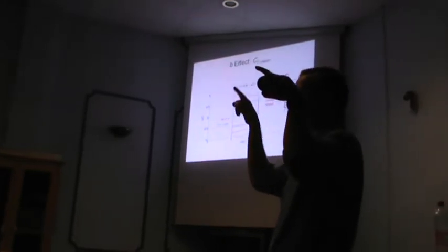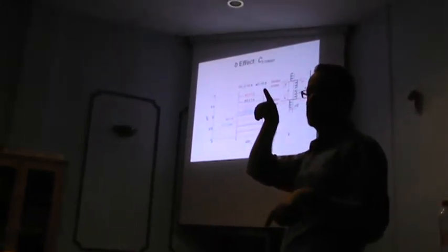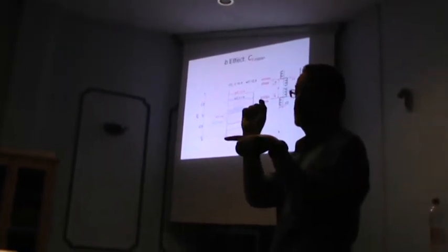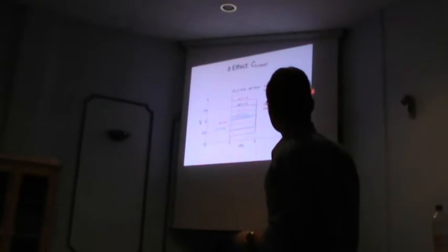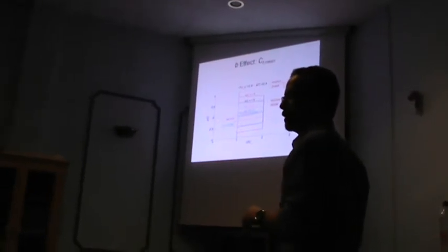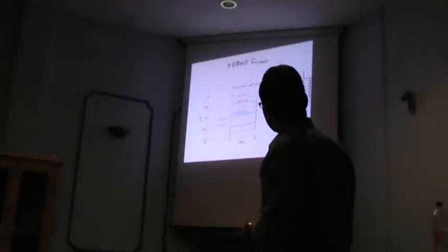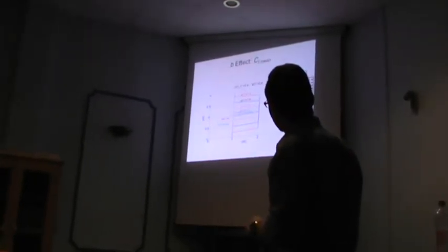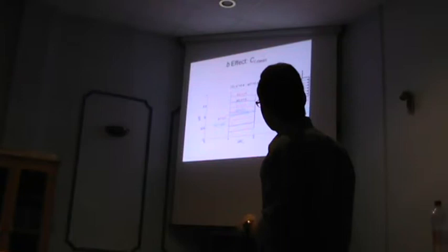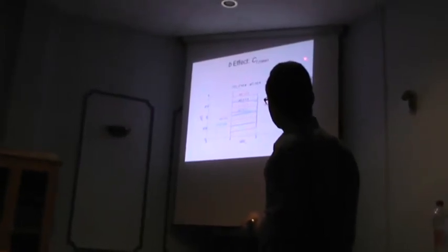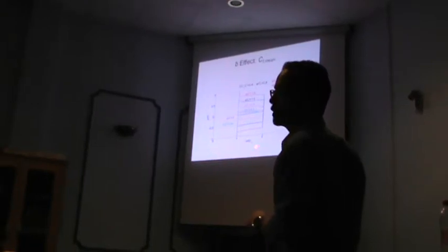In this case, you cannot simply characterize it by circulation, but because of its continuous distribution, you characterize it by circulation per unit length. That's why we use the small gamma. You can think of it as circulation density, if you wish. If you put two vortex sheets like that, the induced velocity of each one will have a jump related to the small gamma, so that the full jump is of magnitude gamma. And with spacing B, when you add the two, you essentially get something that looks exactly like what we have here.